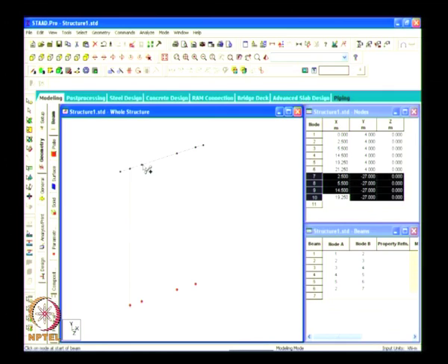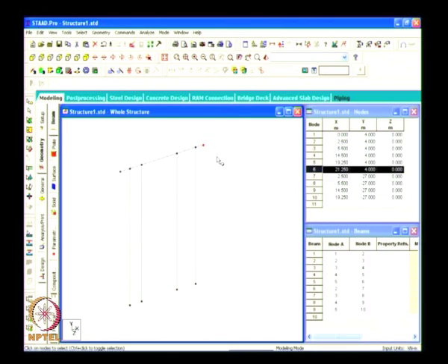It is a pile which is modeled, next it will be the diaphragm wall, this is another pile, this is the next row of pile, then there will be a raker pile. Raker pile means it is an inclined pile.